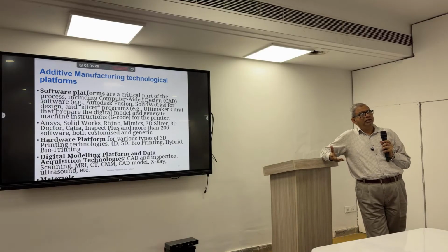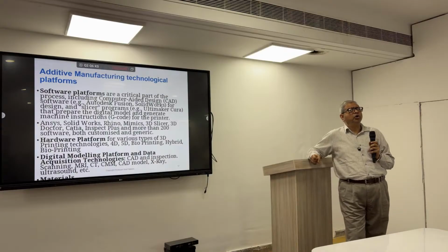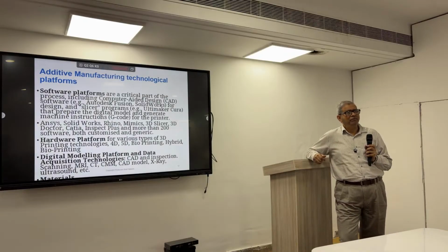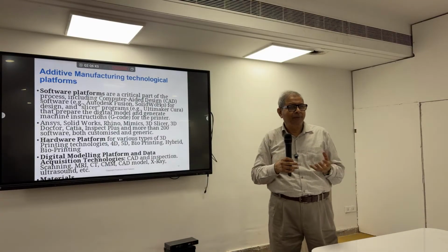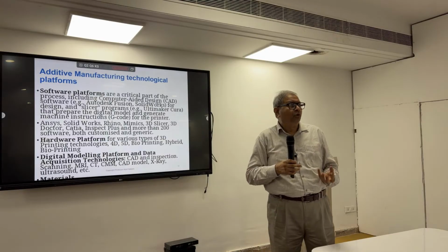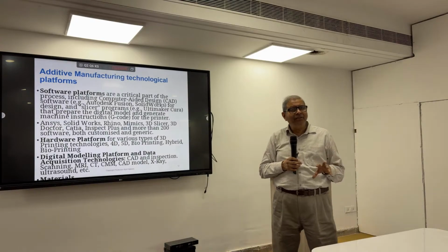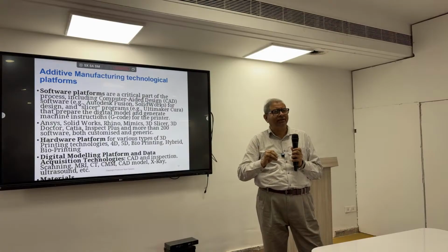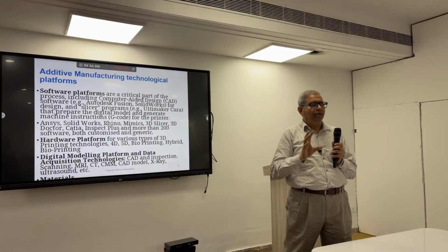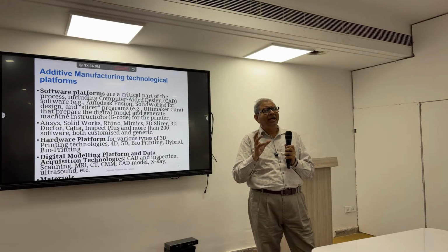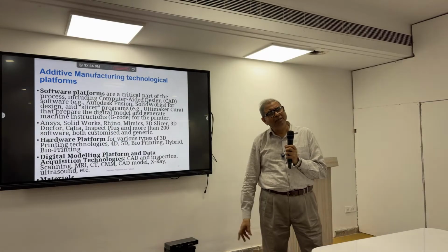अब आप जो कह रहे थे कि प्रिंटर, सबसे बेसिक जो प्रिंटर था वो स्टीरियोलिथोग्राफी था. The first printer that was made was stereolithography. Stereo means 3 dimension, litho means like a stone, so what happened was that there was a resin. When a light falls on that resin, resin is light sensitive, it solidifies on that point, and at that point when it solidifies, it takes a shape according to the light that is thrown on that layer. तो ये आपका पहला प्रिंटर था.